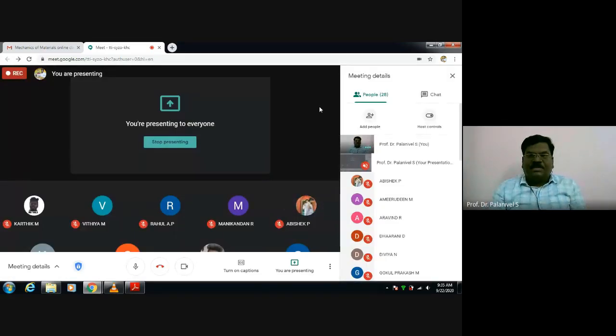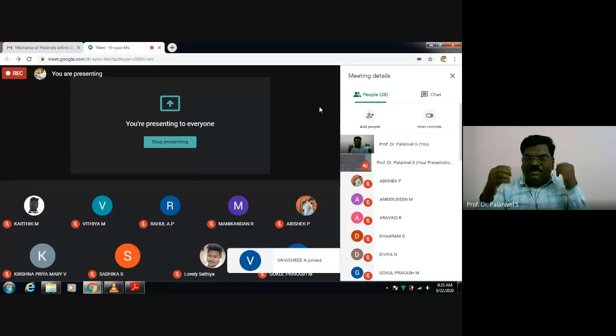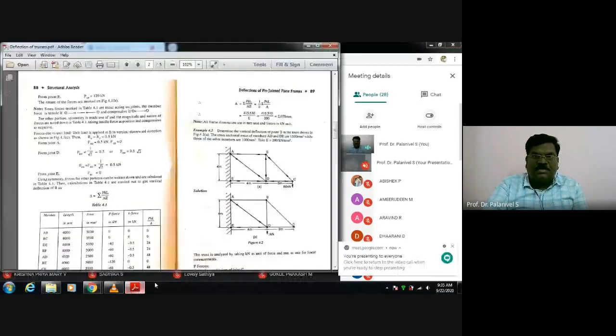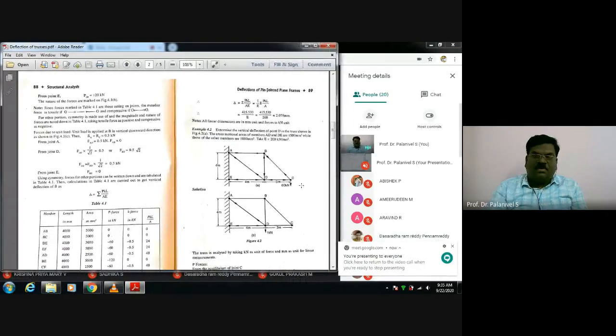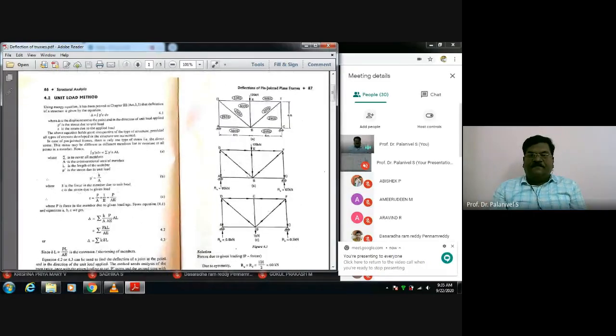Right. Actually, in the second unit, I taught you the definition of process, how to determine it, in the last class. Here I told you twice you have to analyze the truss by method of joints. Given a truss, you have to analyze it twice. What is meant by analysis? First step is you have to determine the support reactions, and then you have to determine the forces carried by all the members of the truss, right?